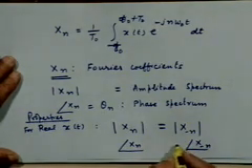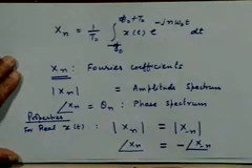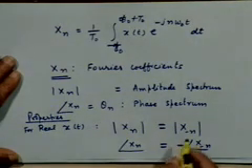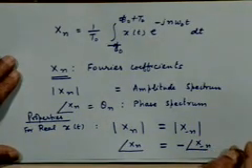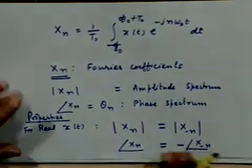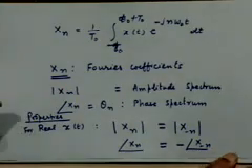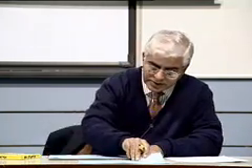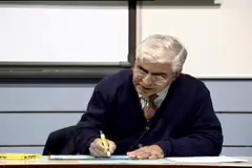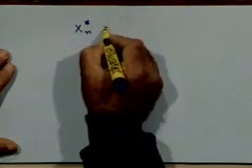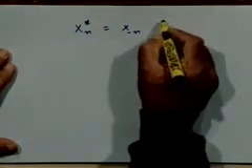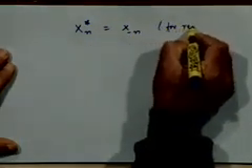They are negative of each other, right? We say that the amplitude spectrum is an even symmetric function and the phase spectrum is an odd symmetric function, not for all kinds of signals but only for real valued signals. This can be neatly summarized in a single equation: x of n conjugate is equal to x of minus n for real signals.